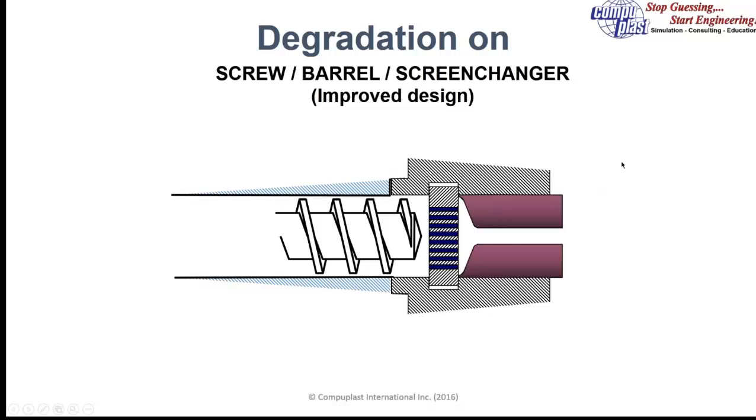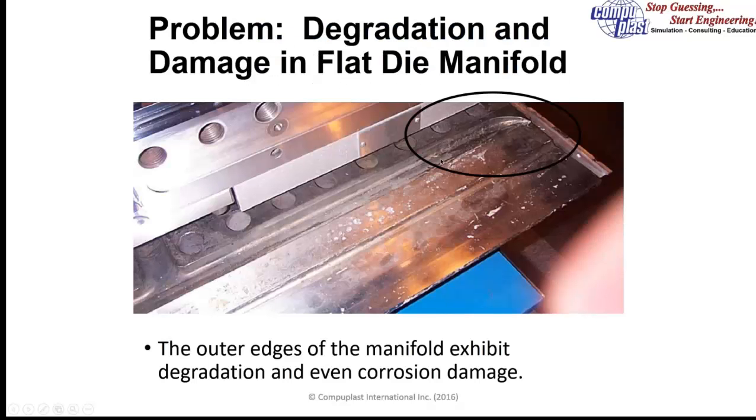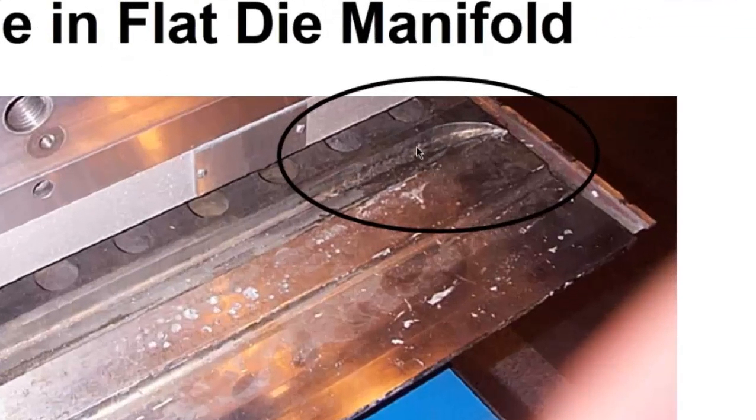Well, by analyzing systems, especially something like a flat die. Here we see a flat die used to produce vinyl siding, and this die had the pitting that occurs when PVC degrades. It forms corrosive byproducts that can get under the chrome and erode away at the base metal of the die, requiring refurbishing. The above picture is the refurbished die. We were more interested in the original after it had been in use for a while, how it had worn out.